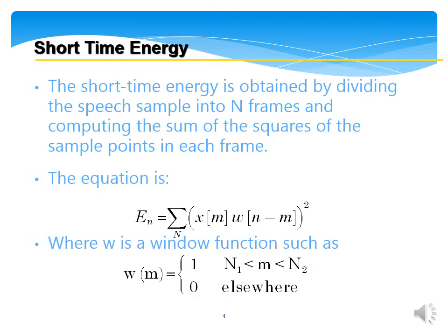problem is when you're speaking, we have vibrations, we have compression and we have rarefaction. The compression causes an electrical voltage of an opposite sign as compared to the rarefaction. So in a sample speech frame, you'll find that you have positive values and negative values. This is at the software level. Once you've acquired it and saved it into an array, we have an average, then we have positive values and negative values. There may all be positive values if, let's say, we have some DC content, okay? And the speech signal, the mean is not zero.